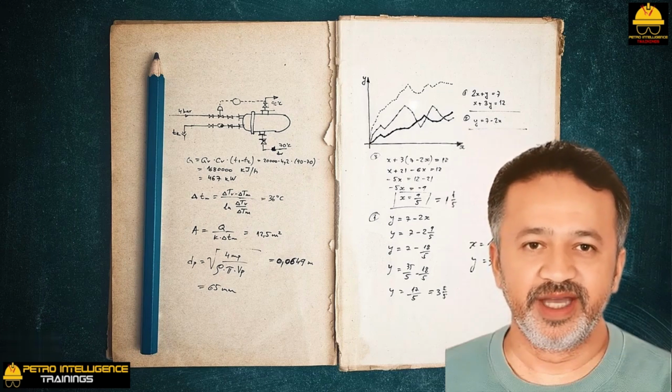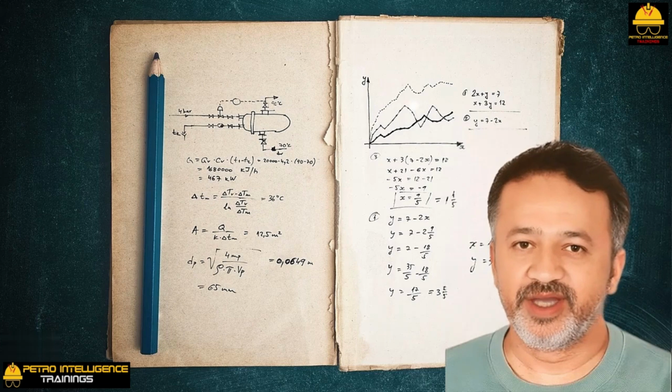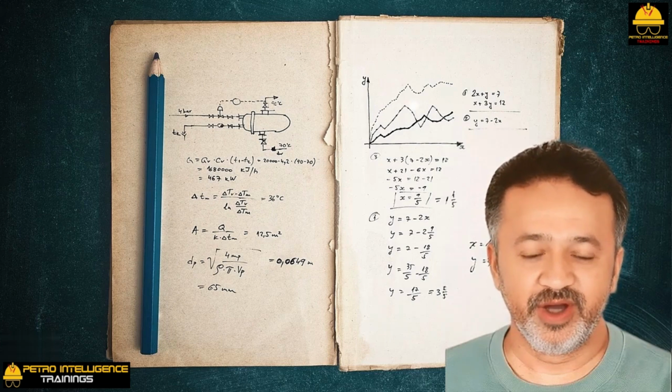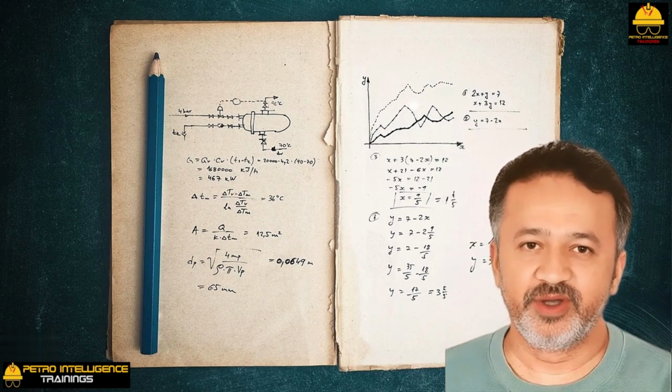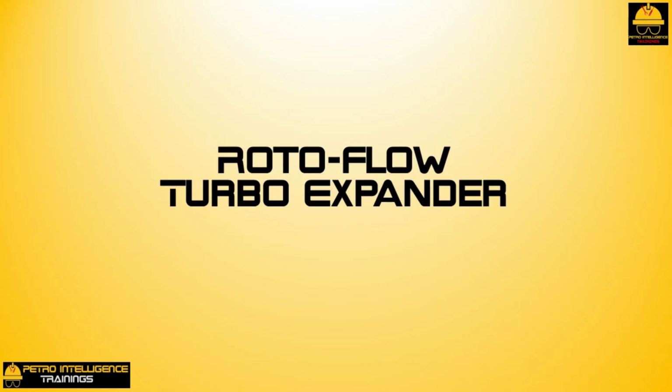As the steam slows down through the diffuser portion of the jet, you would expect the steam to partially heat back up. And it does, perhaps to 200 degrees Fahrenheit to 250 degrees Fahrenheit at the discharge of the jet, that is, at the condenser inlet.